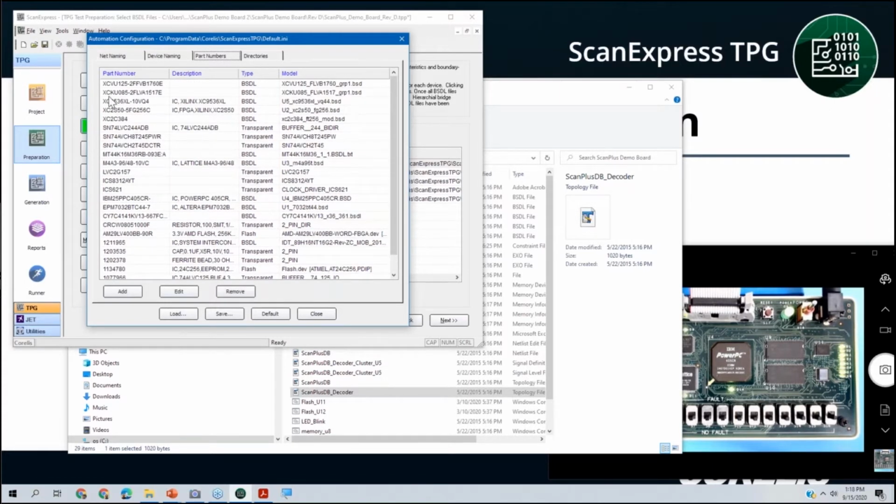As I associate models, for example, as I associated this, let's see, what is that? VU, so that's Vertex Ultrascale from Xilinx. When I did some development with that, it learned that the part number that I have here, and that's based on our BOM convention, you know, the part number is not always exactly the same, will map to this BSDL file. The BSDL file also gets saved on the station so that it can be pulled out later.